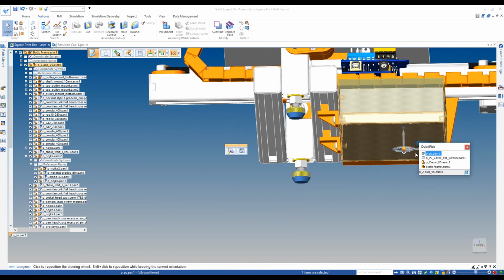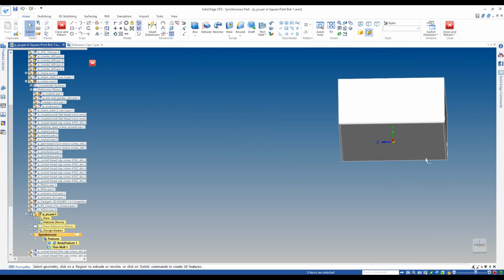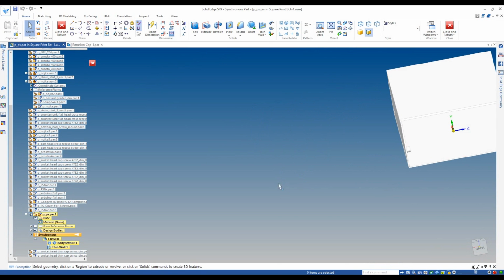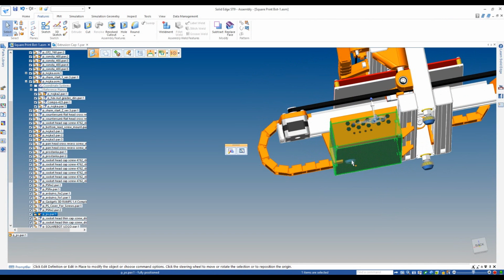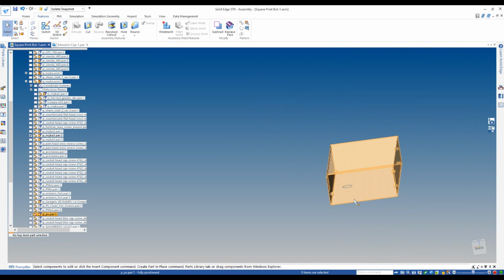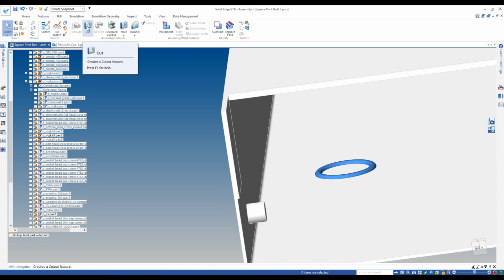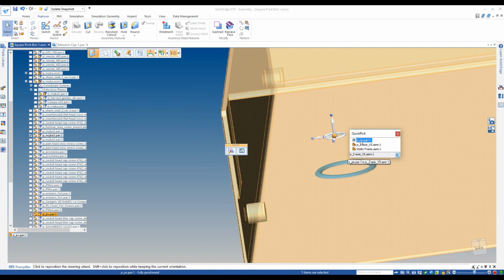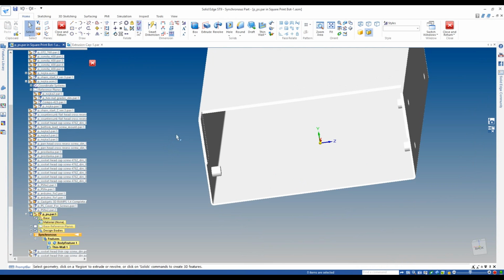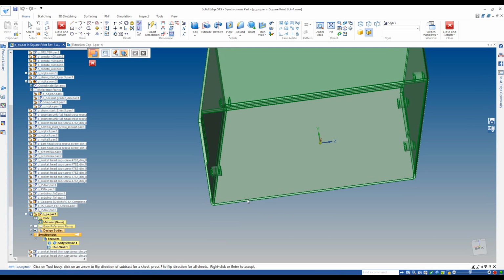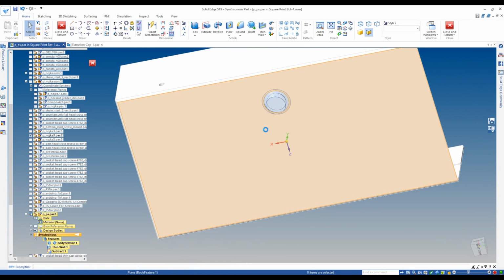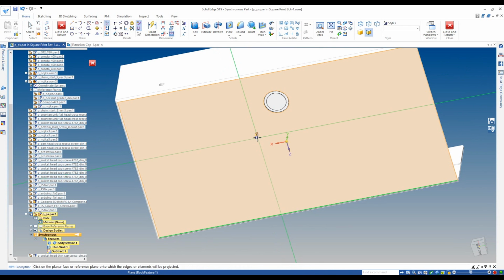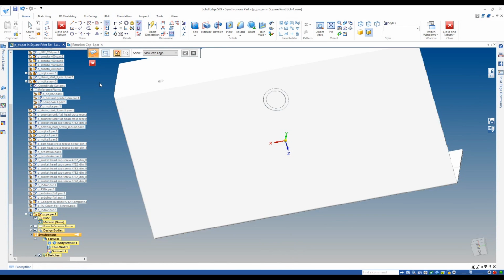We've created that. We also need to add a groove into the bottom of this to fit the silicon foot in as well. So how am I going to go about doing that? Well, for a start, I'm just going to isolate those components so I'm not trying to fiddle my way around. I can see my components nice and clearly, and I can just edit this part, and I'll use the subtract command again. Remove that part. Then I'll just simply clean this up, hide the other components with just a Control Q, nice and easy. I just want to project onto this face, zoom in a little bit closer.